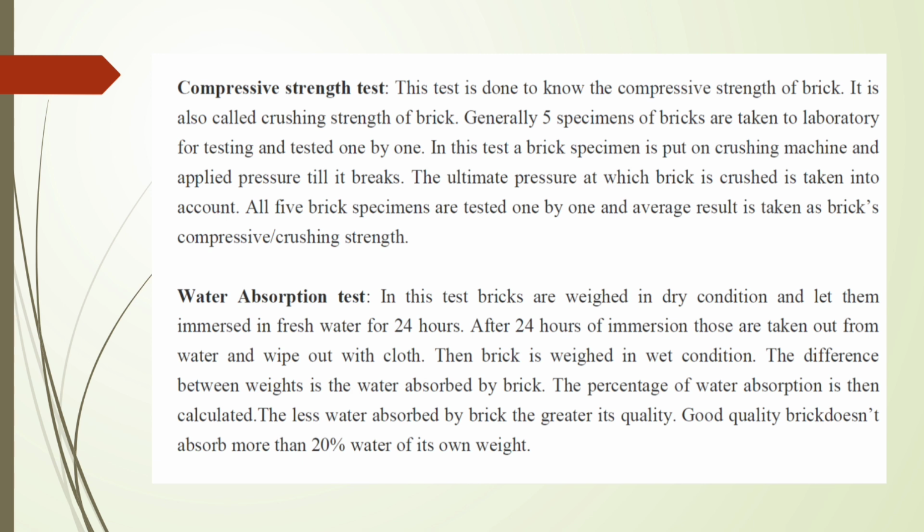Then brick is weighed in wet condition. The difference between weights is the water absorbed by brick. The percentage of water absorption is then calculated. The less water absorbed by brick, the greater its quality. Good quality bricks do not absorb more than 20% water of their own weight.